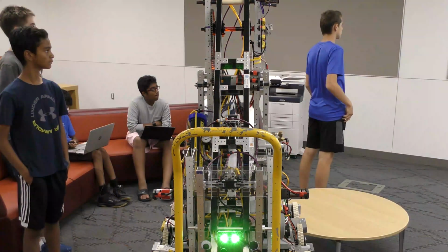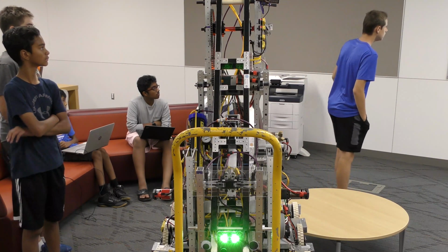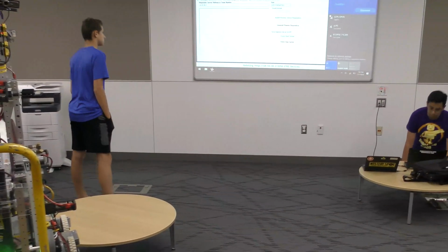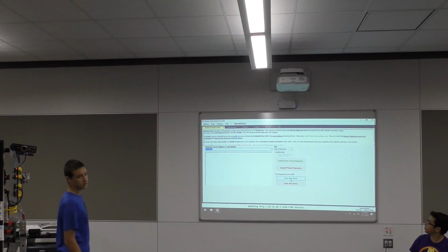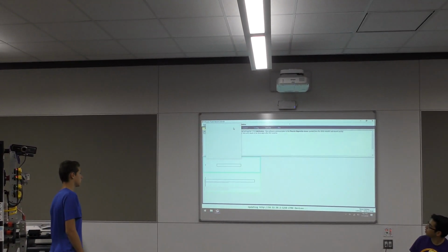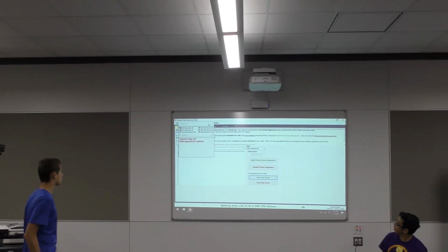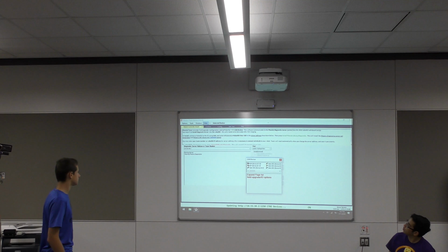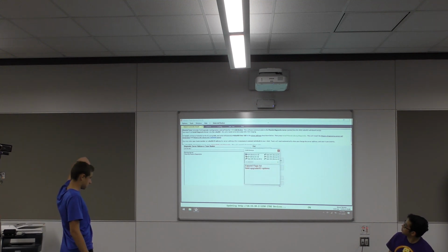Okay. So this is what Phoenix Tuner looks like. It's just a little widget. Once you open it up, make sure you're connected to the Team 5338 Wi-Fi, and you can click force start the server if it didn't start. Once it says okay, the server started, you should be able to click CAN devices and it'll open up a page like this.